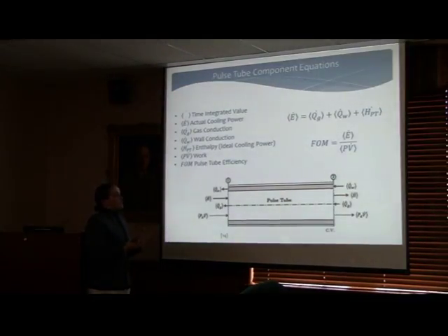So these are the basic main equations that we have for the post-processing. All of our values are time integrated. And then this is going to be your cooling power, so this is the first thing that we look at. It's going to be the time averaged enthalpy, including the losses. These are going to come out negative from the fluid, and these are going to be the losses associated with the wall and then the gas itself. As you can see from this image, these are losses.